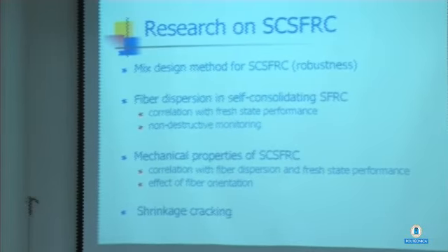First of all, we tried to assess a rational mix design methodology for steel fiber reinforced self-consolidating concrete. After that, we looked into correlating the fresh state performance with the fiber dispersion, and also developed some non-destructive methodologies to monitor the fiber dispersion in the structure, which can be useful for quality control when you go to the factories.